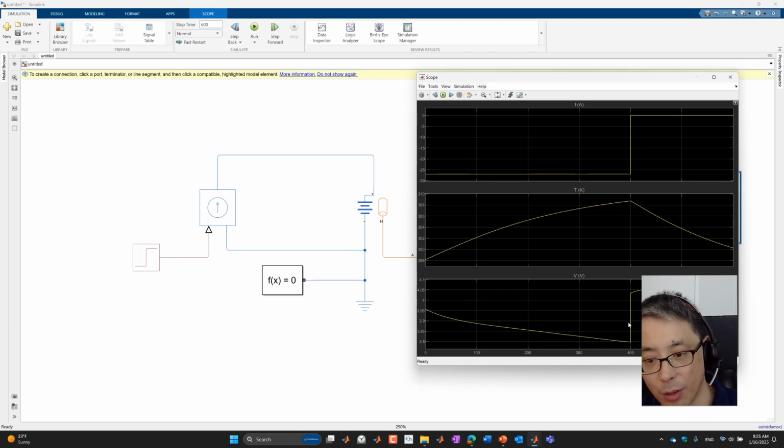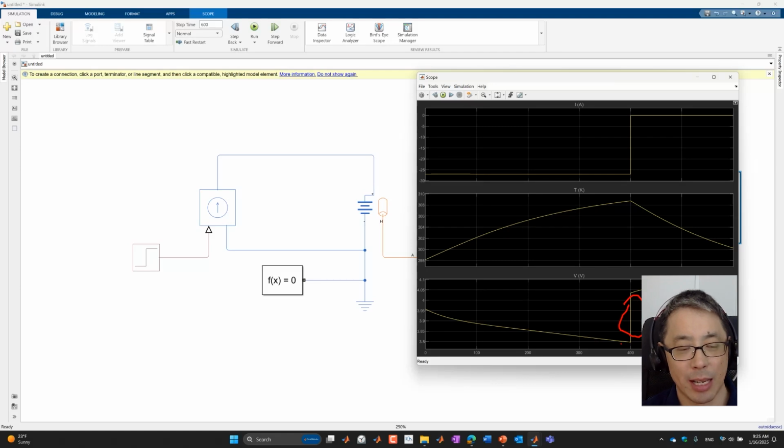So in other words, if you do a proper parameterization for your cell, you might not see as much instantaneous recovery. So that's number one. Number two is that for battery measurements in the lab, all the testers have a response time, typically about dozens of milliseconds, and also a smallest time step at which the tester can log data.